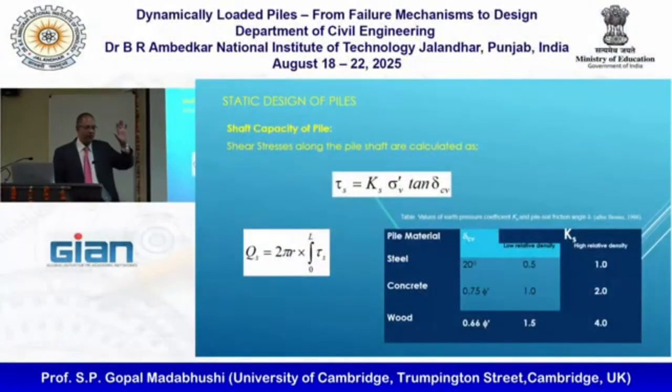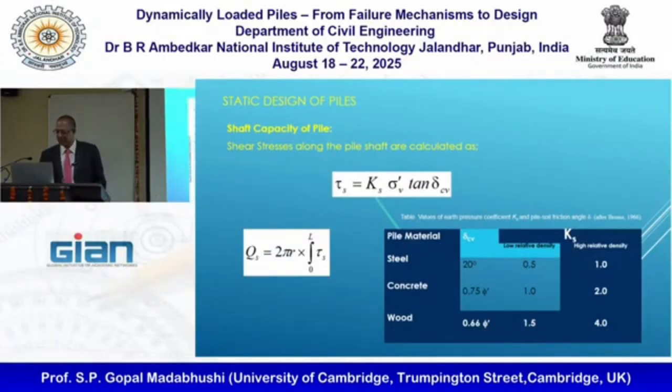No, these are all just for vertically loaded piles. I'm only talking about that for now. Okay. But initiation will be the same whether it's compression or tension. The only thing that changes is if I'm going to pull out, then the cavity will collapse and then my earth pressure will collapse. That is at the failure state.